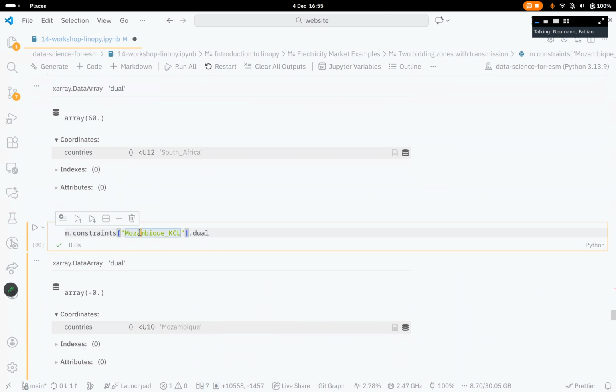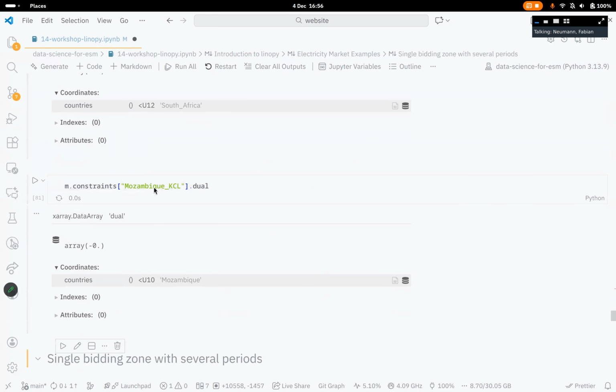It's because if you have the ability to consume more power locally, there's still a little bit of capacity left of the hydro unit to supply the local demands. So there, the price would be 0. Whether it's shown as -0 or 0 can sometimes go this way or that way. It depends on the solver accuracy. Basically, they don't solve to full optimality, but they always have some numerical tolerance. So it can be that it's slightly negative.